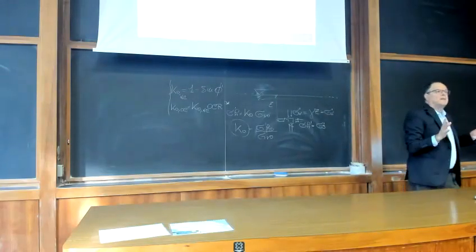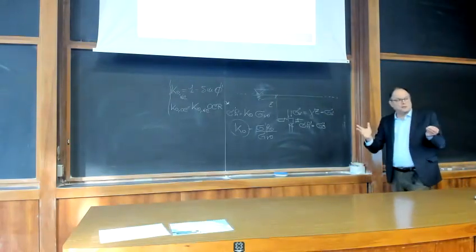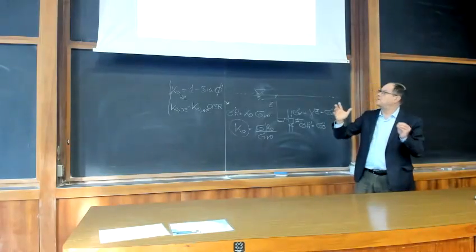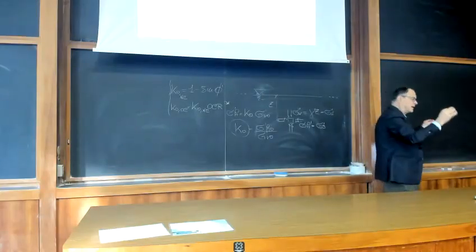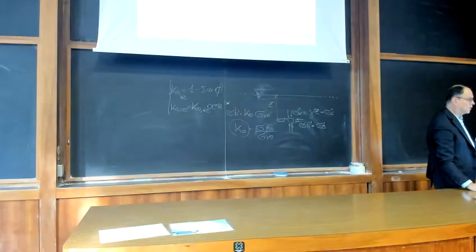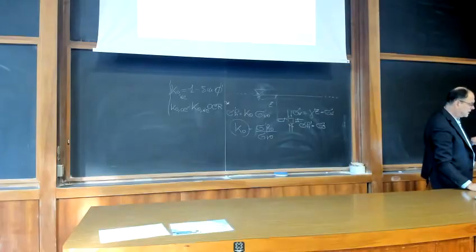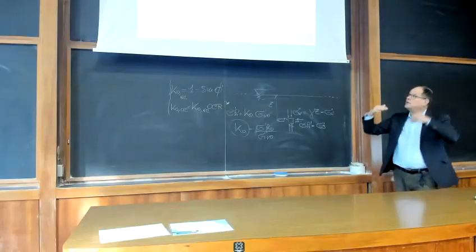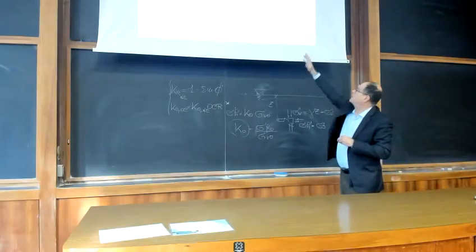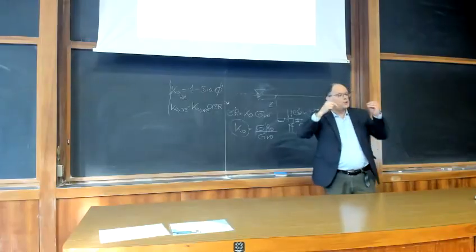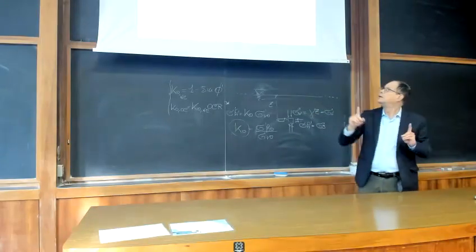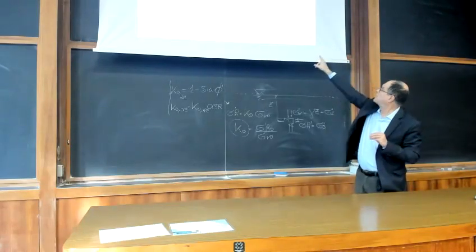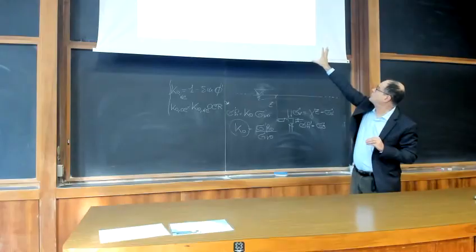As I said, the horizontal stress is not statically determined, it can be any value, but it is limited by the limit lines, which are defined by the Mohr-Coulomb criterion. So you can see that this circle can be any circle lying below the limit line. At limit, you have only two circles that are tangent to the limit line, to the Mohr-Coulomb failure criterion, that you can see on the right-hand side. So you have two limit conditions.